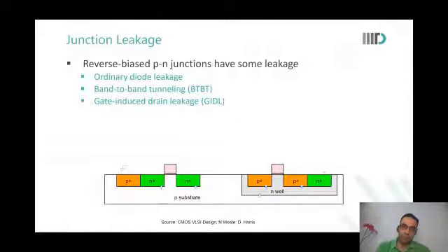All the NMOSs are in the same P well, so their body is at ground, but their source is at Vx or Vz. So effectively, those transistors are in reverse bias because source voltage is higher than the body terminal voltage.